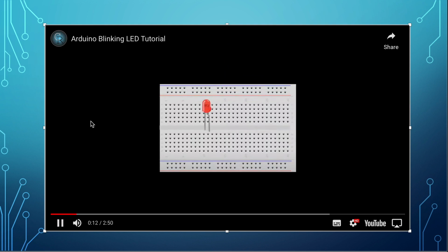So now you can see that this LED will be fixed to this breadboard, and you can see these middle columns over here. What you need to know practically is that along this line, and along this line, are internally connected, right?